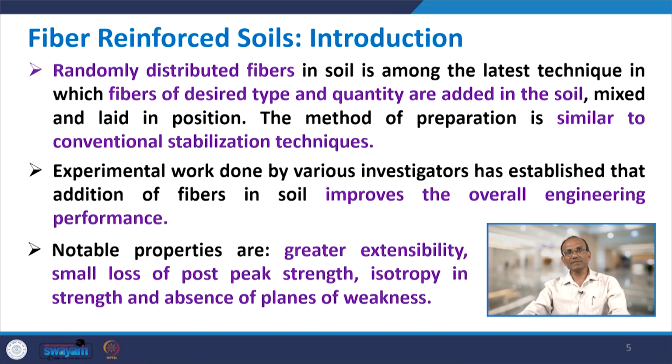So, an introduction about fiber reinforced soils. Fibers are said to be more effective when they are randomly distributed. Randomly distributed fibers in soils are among the latest techniques, in which fibers of desired type and quantity are added to the soil, mixed and laid in position. The method of preparation is quite similar to conventional stabilization techniques. So, here you are mixing the fibers inside the soils.